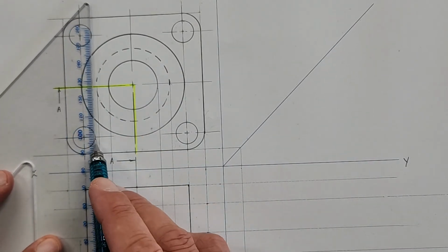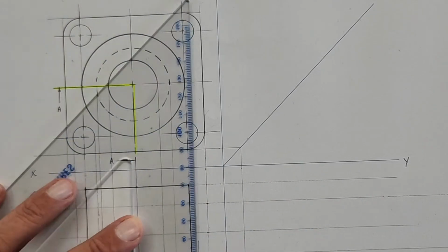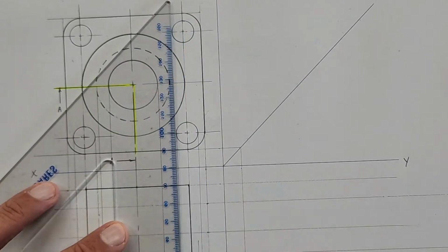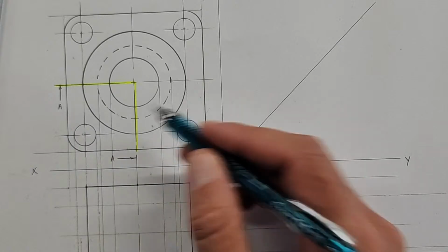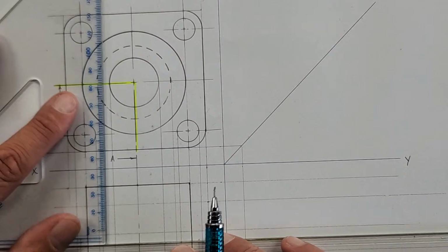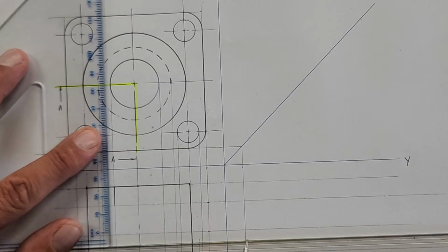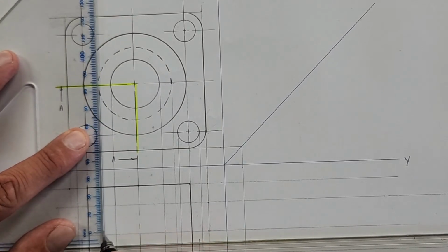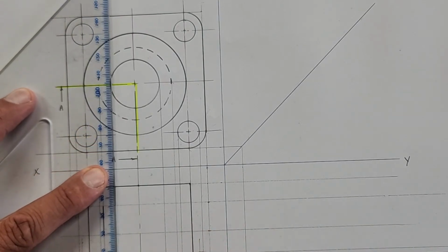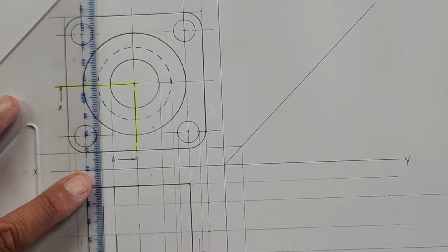Also the outside of those lines. Okay, now I start looking at what do I see. If all of this falls away, I'm going to see that inside, so I can know that's going to be nice, and you can see that edge there, and you can look at the front view that's given if you want to double check me. Okay, in line here, there's a step there, then I come back, and then there's again